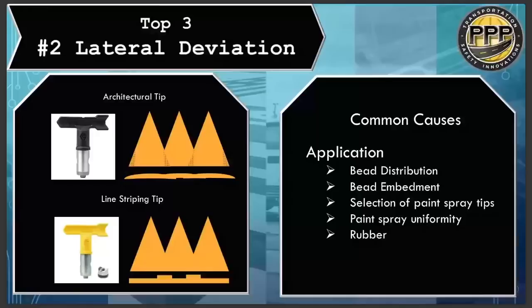It's kind of going back and forth. When you're doing a larger format, we recommend going with an architectural tip. Let those overlap nearly 50% or so, and then you're going to get a much more even flow of paint and volume of paint. There are wet mics out there, wet type.